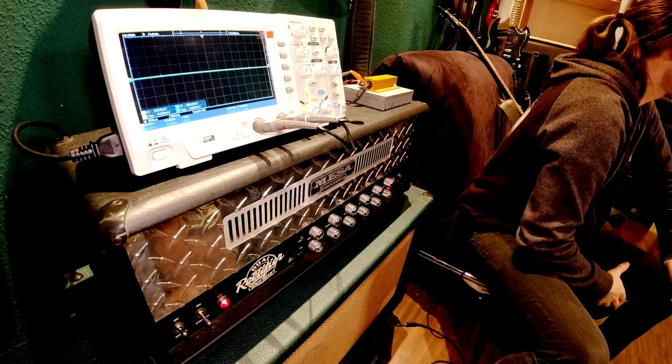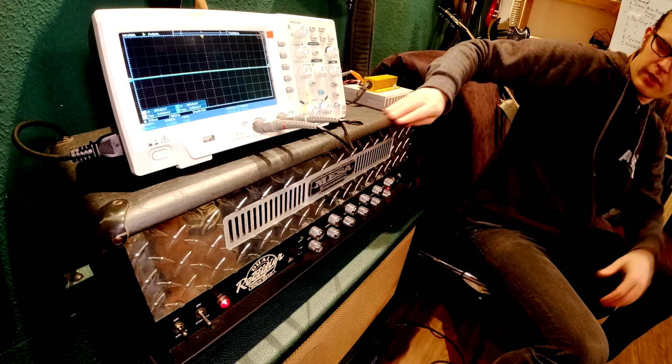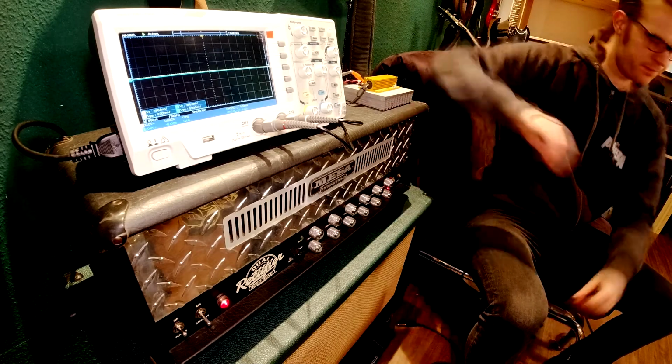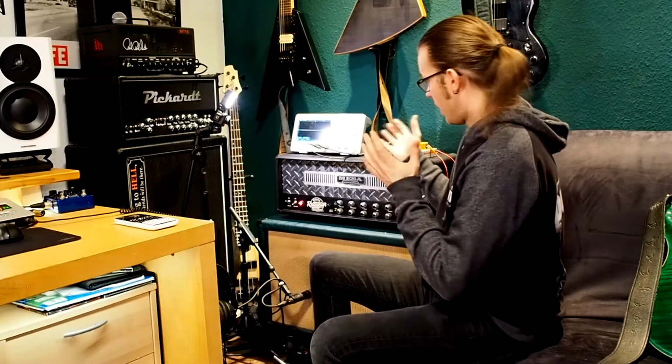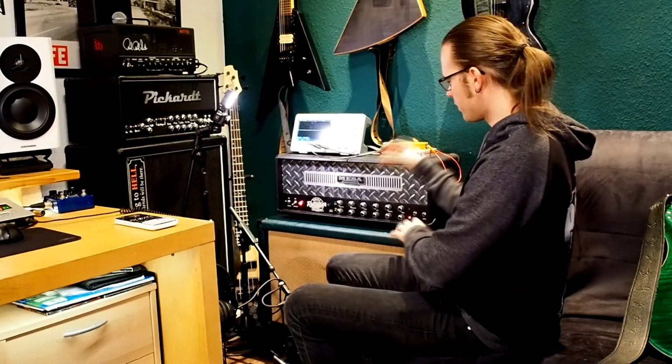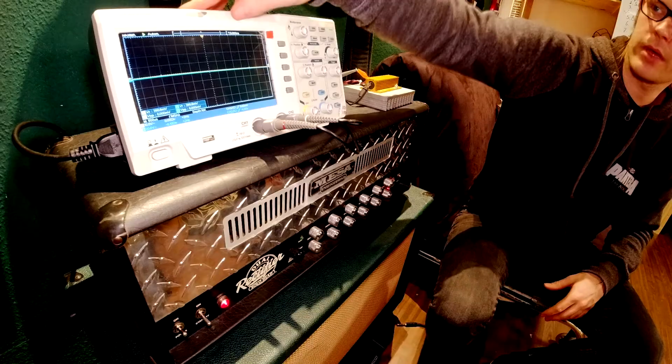Okay, let's get our hands dirty with this beast of an amplifier, the Mesa Boogie Dual Rectifier in the 2-channel version. It has 4 6L6 output power tubes. They should deliver around 100 watt, but let's find out with our new formula that we have learned and with that mysterious factor 0.707. I have a dummy load here with 15 ohms. It can handle 150 watts, so it should work with that power amp, and my oscilloscope.